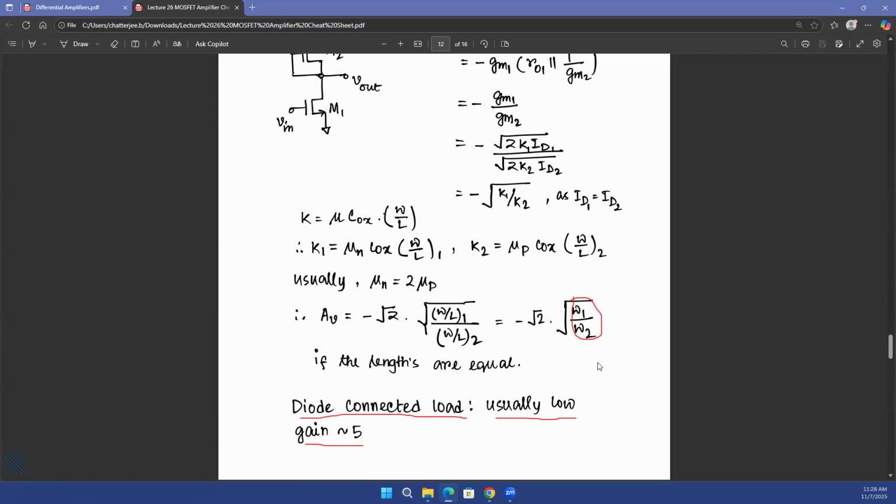Generally, if you are trying to place a very small transistor close to a very large transistor, you have a hard time laying out and connecting all the inputs and outputs because you have to draw long routes. Those long routes will have parasitic capacitances, resistances, and so on. So it's generally not recommended to have two transistors, one very big and the other very small, very close to each other. You cannot really have one transistor 1,000 times larger than the other. It's almost impossible. And of course, your formula will not work because of all those parasitic capacitances and resistances.